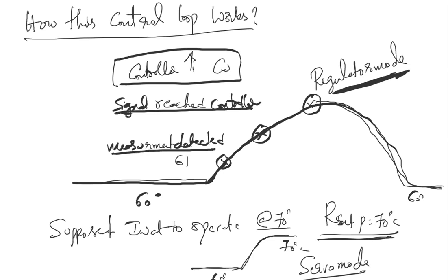So clear. The controller basically comes into the picture in two scenarios. One is if there is a disturbance. Second, now everything is steady state, and the controller doesn't do anything. When the system is in steady state, the controller doesn't do anything. Suppose suddenly you go and change the set point intentionally, then also the controller will come into action and make the control variable equal to the set point. So these are the two ways in which the controller will come into the picture.